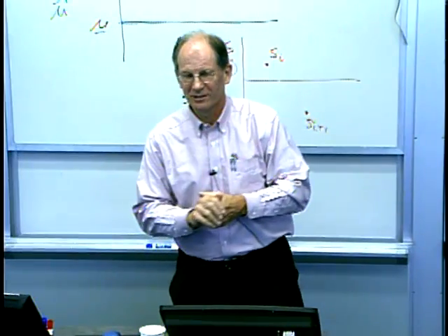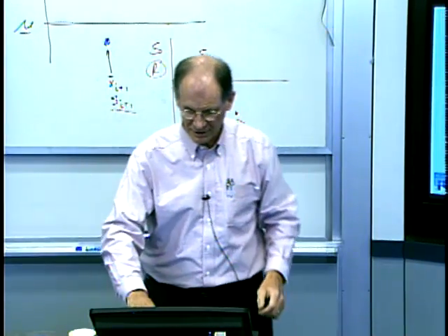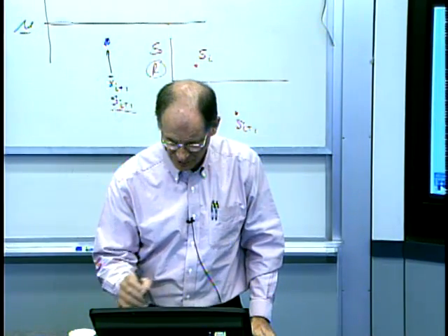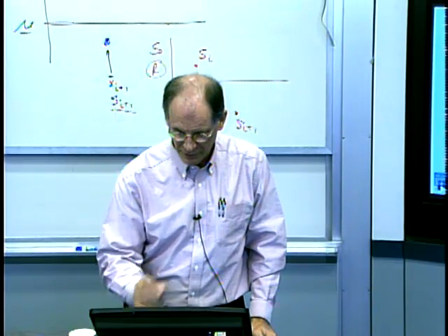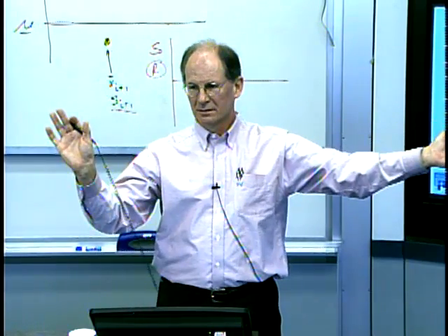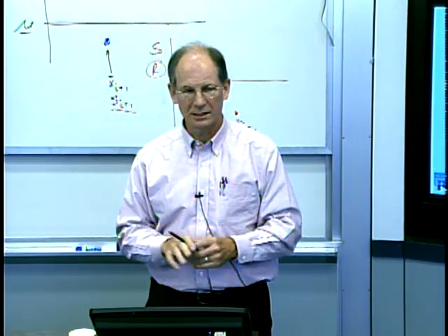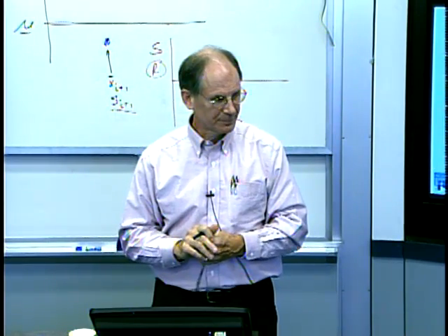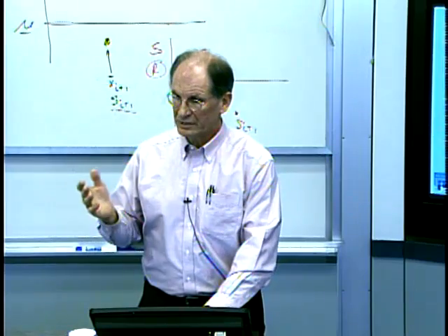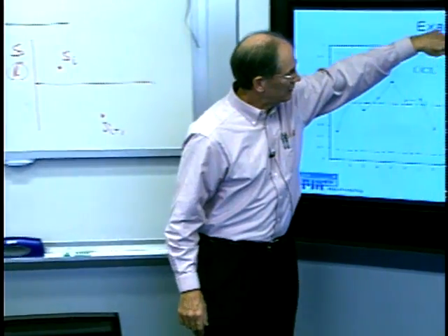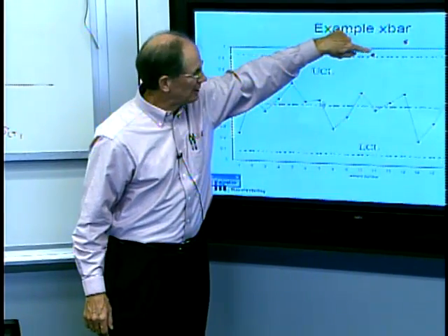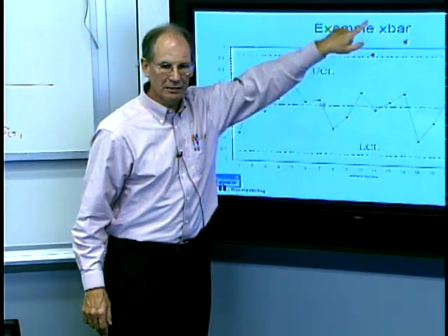So a simple SPC thing, and one you hear about all the time without much thought, frankly, is, oh, there's a data point up there, or there's a data point up there. Impossible. Shut down the process. Everything's wrong. You can see that's a good first order thing to do. There's only 3 chances in 1,000 that one would be out there, outside of these 2 limits. So that's a pretty good first cut.